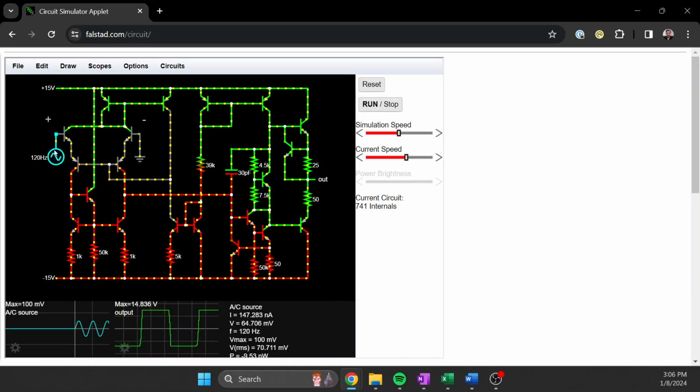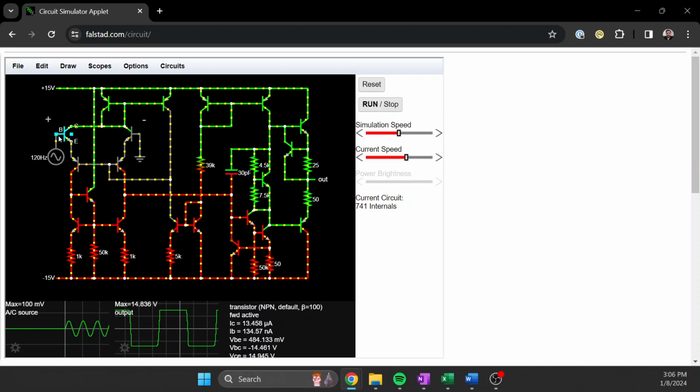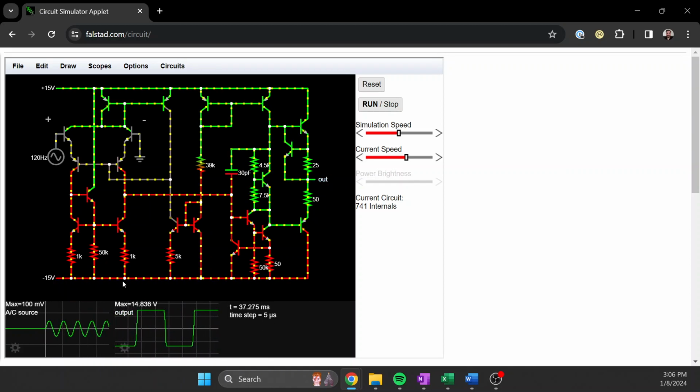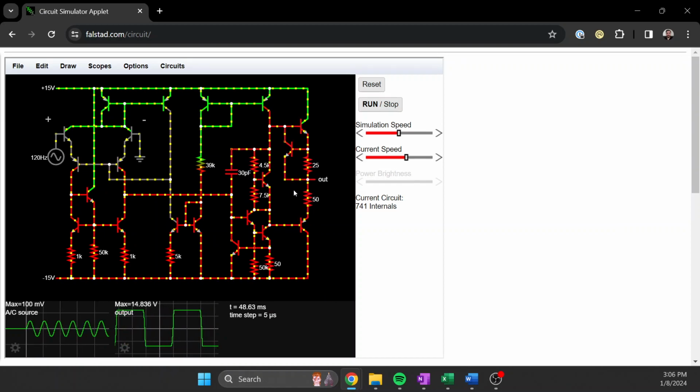The input voltage here is going to the positive input terminal, the non-inverting one, so the square wave is in the same phase as the sine wave. That's another application of comparators. When you use AC, you are able to get a square wave out of it, which can be really useful in a lot of applications.